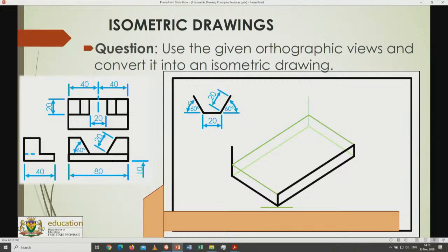Once you're done with the auxiliary view, you know that 60 degrees and 60 degrees, and you know that diagonal distance is 20, but you don't know what the height is. The distance between the two is 20, and that starts exactly in the middle, so we know it's going to be on that 80 millimeters. It's going to be starting at that point, 20 in total, so 10 to the left, 10 to the right to find the starting points. But now this, like I said, is 60 degrees and it's already standing on 30 degrees, so we can't do the calculations. Do the auxiliary view.